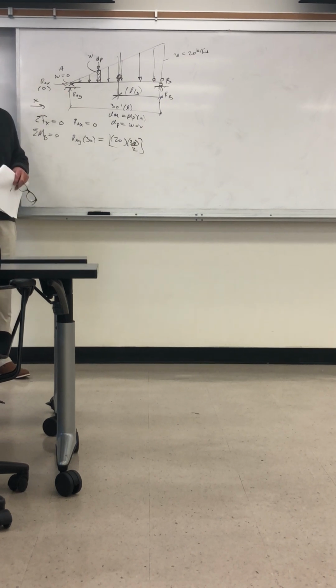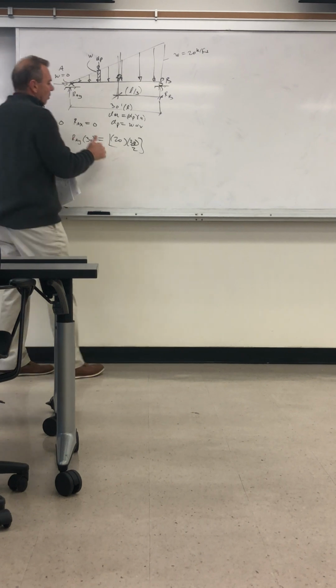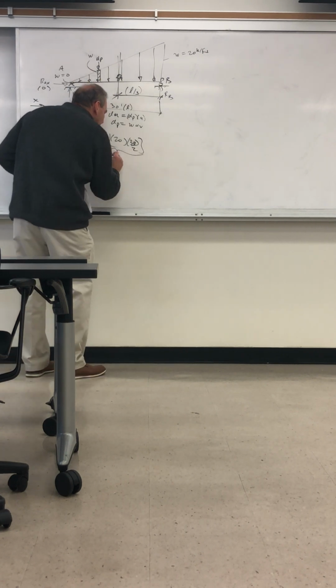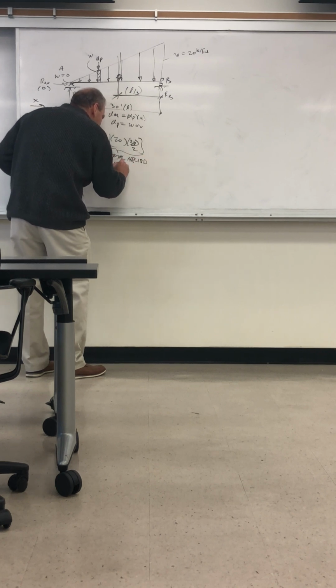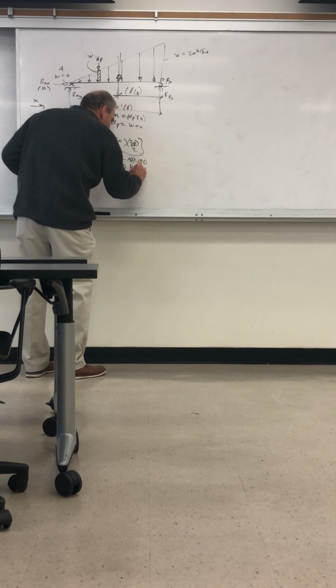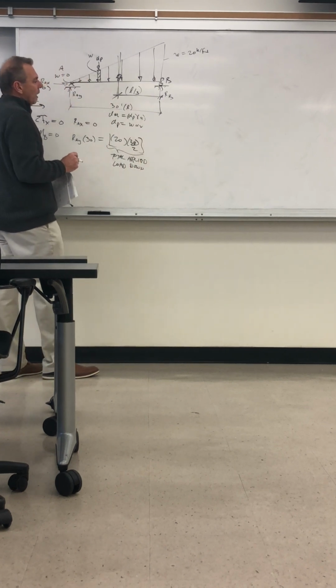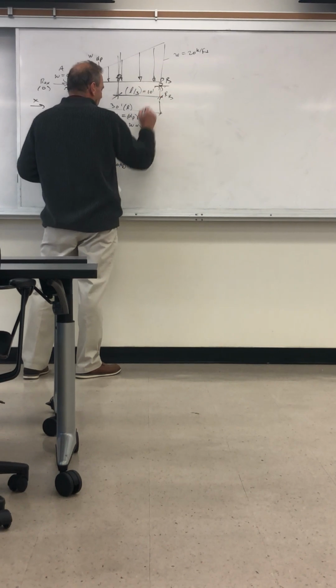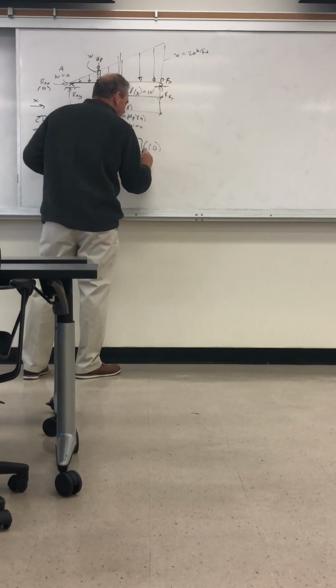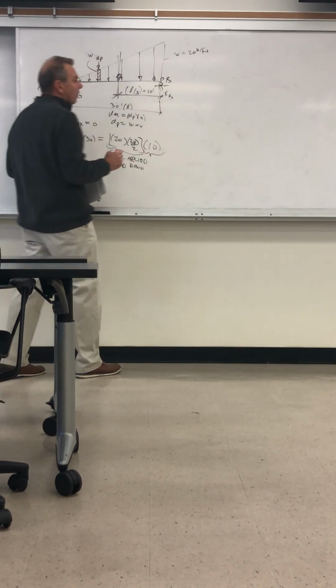That's the balancing point. And so what we do is take the total applied load down, and then we multiply it by the moment arm, L over 3. This is equal to 10 feet, right? So multiplied by 10. This is the moment arm about B.